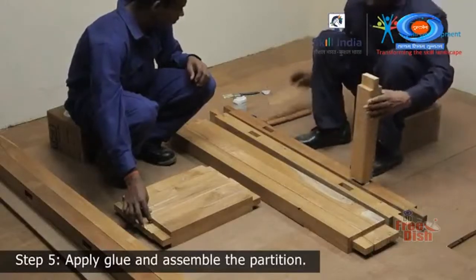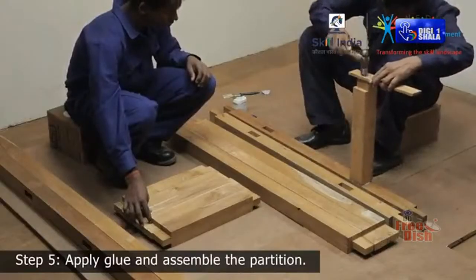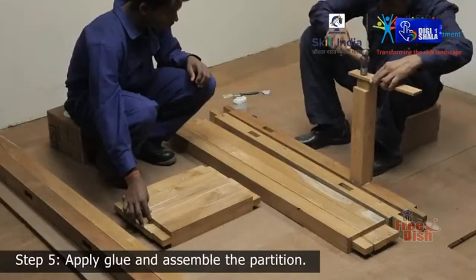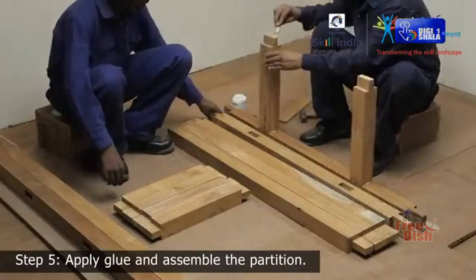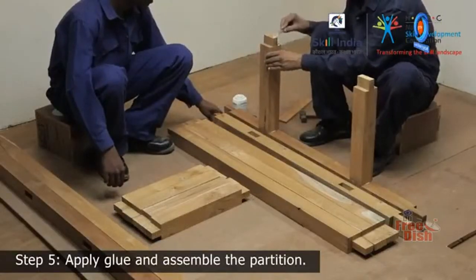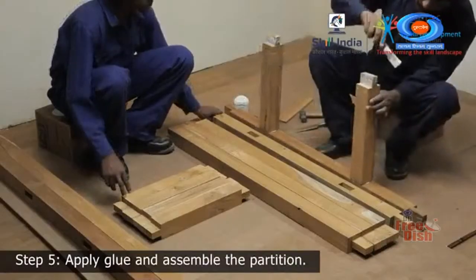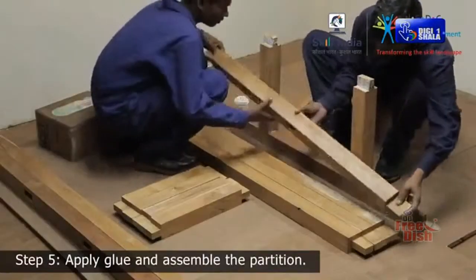Remember, do not use the hammer directly on the workpiece as it may leave marks on them. Place a piece of scrap wood in between. Then apply glue onto the tenons of the fixed noggins and into the mortise of the other stud member and fix it onto the tenon of the noggins.